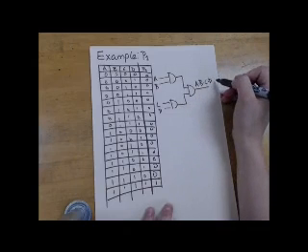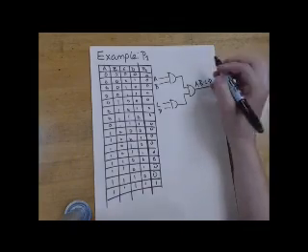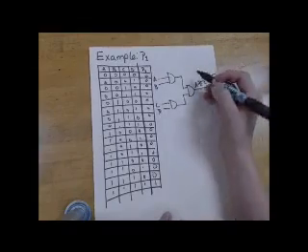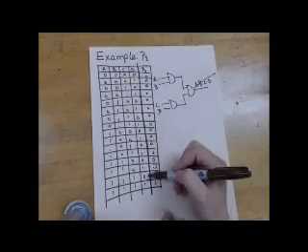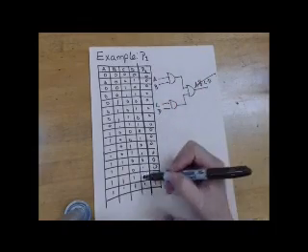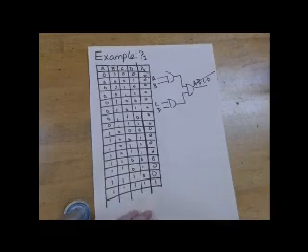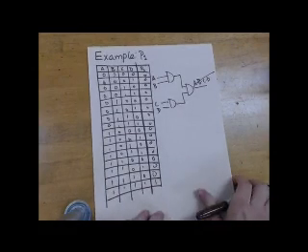AND gates do multiplication, so if you see all of these multiplied together, you're only going to have a high input 1 if all 4 are 1. So if any of these inputs are 0, nada, this will be 0. Which is, when you see, if any of them are 0 here, which are the first 15 entries in this truth table, we're going to have 0. So, we already saw that one earlier. That was the one we did a couple of pages back.